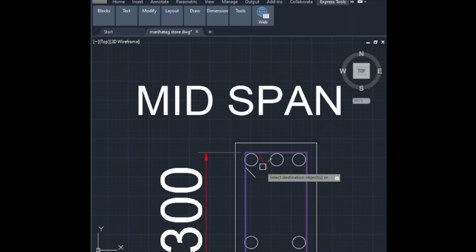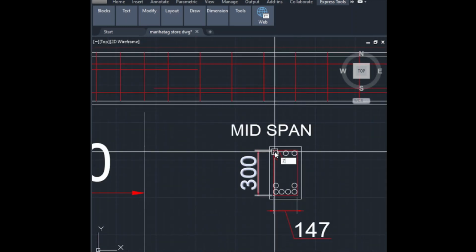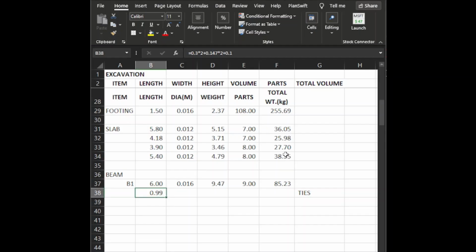Like that. So we'll count this one together. It is 0.1. Okay. But as I said, guys, this is only a rough estimate. If you will be doing your estimate, especially for the quantities, you need to refer to the cutting list of the drawing or the plan. 0.2, 0.3, so this is 16 mm again, and the weight is that one.